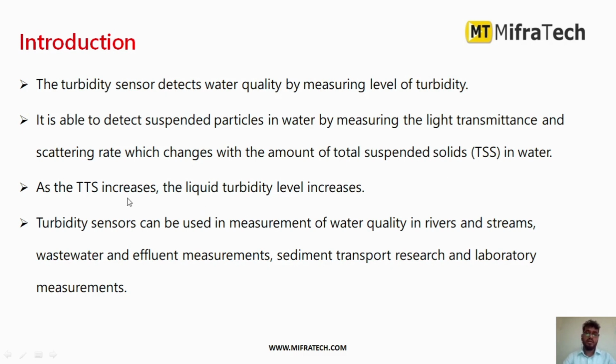TSS is nothing but total suspended solids. When the TSS value increases, the level of liquid turbidity also increases. So when the amount of total suspended solids increases in the water, the amount of turbidity also increases in that particular water or liquid. Depending on the amount of suspended solids, it measures the turbidity.